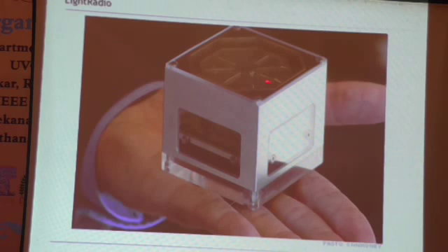If you need larger capacity, you can stack several of such systems and use them. That is how the integration has reached such a level that the base station has been brought to a size that you can even hold in your palm. Then the whole thing can be mounted right there, and all the RF losses are reduced, because the cable length is now reduced. Only the digital signal will come down from here, and digital signal losses will be nothing. You can run as long a wire as you need.